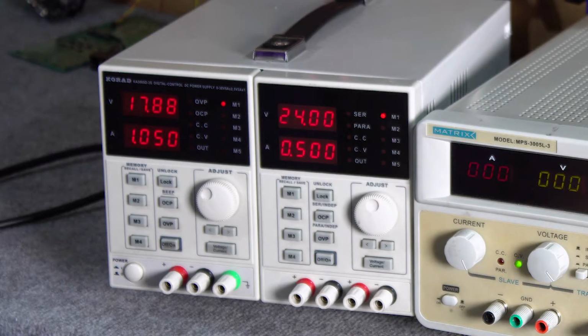Let us consider the situation where we require the supply of several amperes to our system. It may turn out that, through the voltage drop on the wires, the tested device will not work properly or we will not be able to check its most important parameters. The built-in voltmeter measures the voltage at the terminals and not at the ends of the wires.